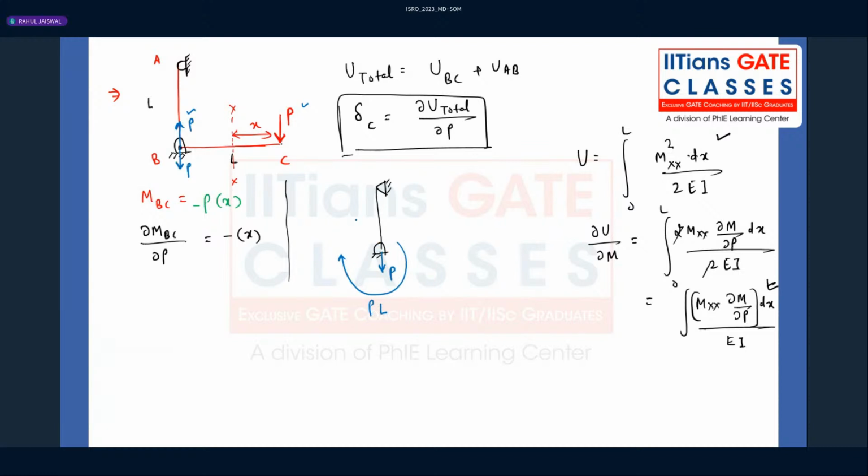Now this particular beam will be a simply supported beam subjected to an end moment. One end has a moment acting, but it acts like a simply supported beam. We have to calculate the reaction forces, say RB and RA. I'm converting it into an equivalent diagram. Here there is a P and a moment PL. I have simply rotated the diagram by 90 degrees; the actual diagram is vertical, so do not confuse. Here A, B.